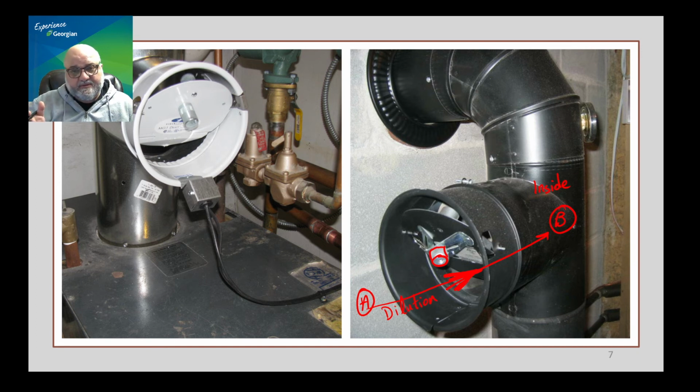And there is one exception in the code book: in the application of an incinerator, we don't use a double acting barometric damper. We use a single acting barometric damper because flue gases of the incinerator are of biohazardous nature, so they might have toxic material, or who knows, even if it is in the first phase of burning, because it has many burners, the combustion products might include some kind of pathogens that can create health hazards.